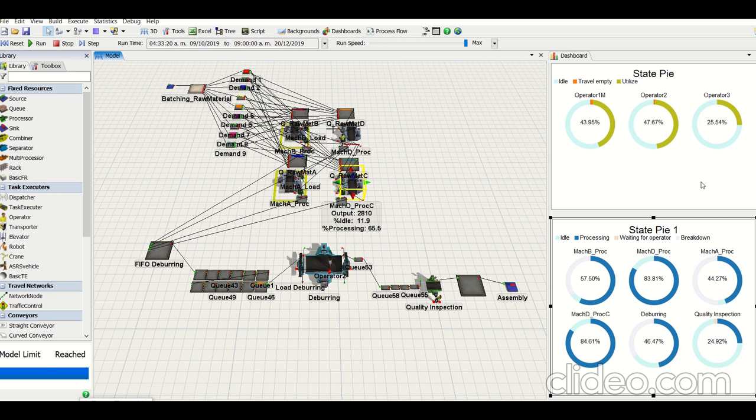However, this is not completely right if it is considered from the idle time perspective, which also takes into consideration machine breakdowns. The only one in which the idle time exceeds 33% is quality inspection. Therefore, we decided to schedule that particular operation in only 2 shifts, and we still had enough idle time of the machine and operator to reduce an additional shift.